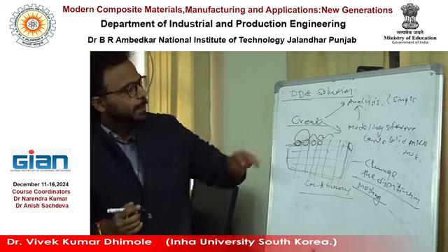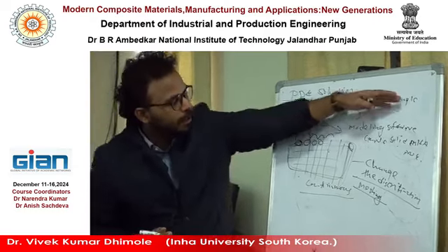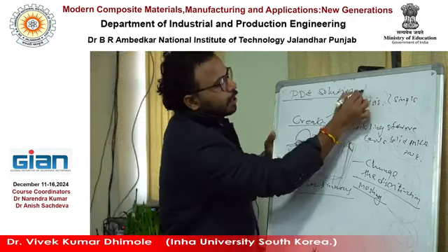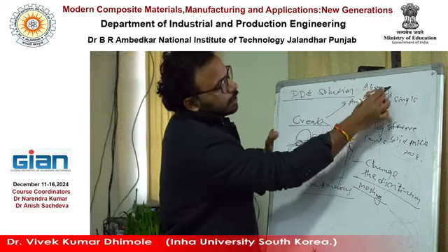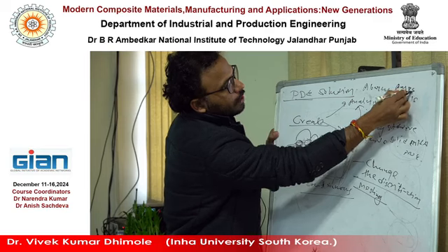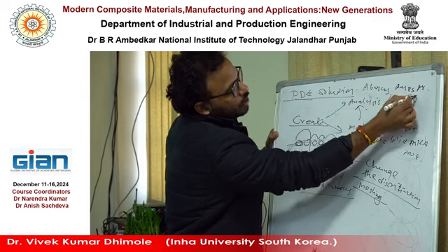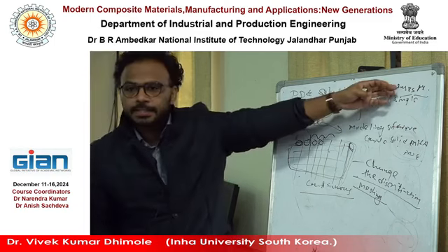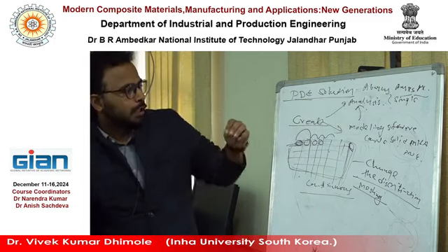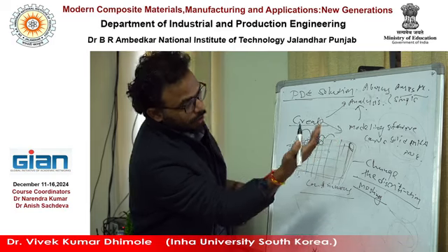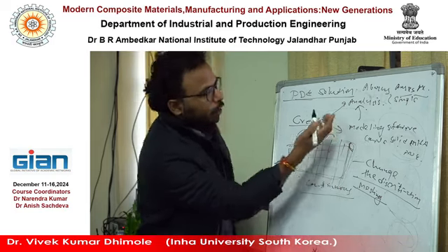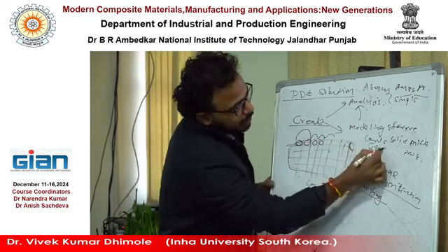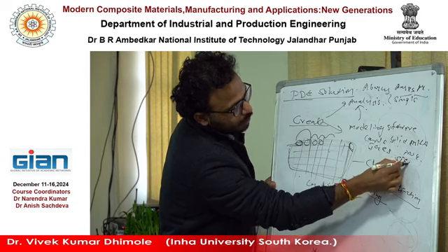So the first thing is to create the model, either in a simple way in the analysis software only, which can be Abaqus, ANSYS, NX Nastran, and many more. The popular ones are Abaqus and ANSYS, right? If it's a complex one, you can create the model elsewhere and import it. The importing formats are IGES and STEP.